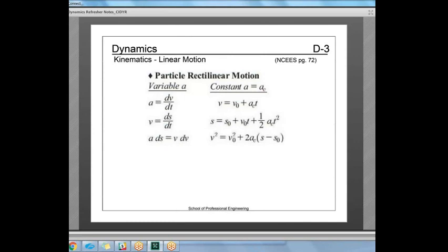And if it's radians per second, then whatever R is, if R is in meters, then V is going to be in meters. Okay, so the linear things like S, V, A, and R have to agree. In other words, you can't have kilometers in one and expect meters to come out. If one of them's meters, the other's meters. But theta, need to get it down to radians. Wherever you start, convert it to radians. Omega, convert it to radians per second, and so on with radians per second squared.